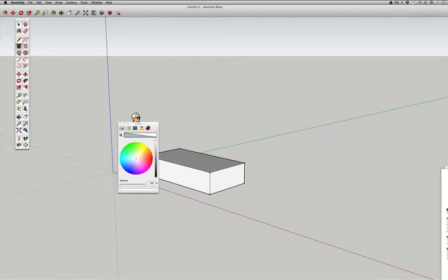Now, when you do that, if it's a polygon, it's going to ask you multiple sides, but a circle automatically defaults to 24 sides, because really a circle is a 24-sided polygon in the world of SketchUp. So I'm going to click right here, say. Then, when I start to pull out there, I can type in the radius. I'm going to say a radius of 5,000,